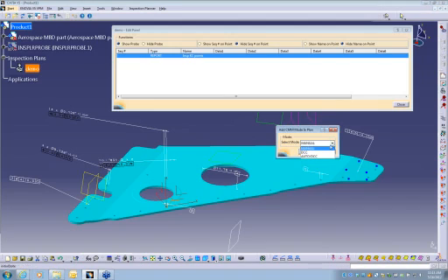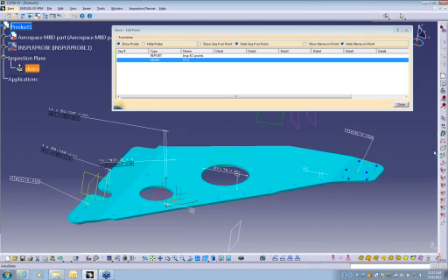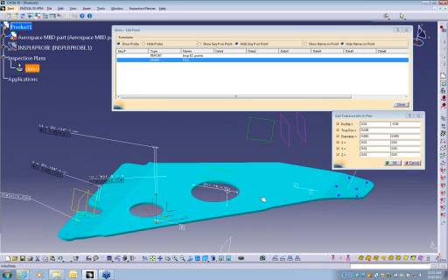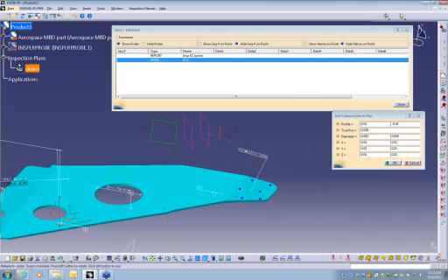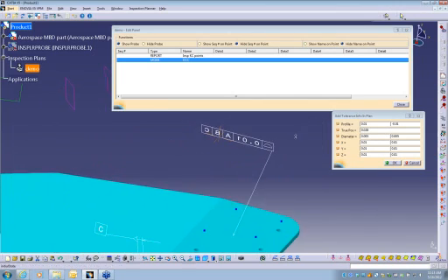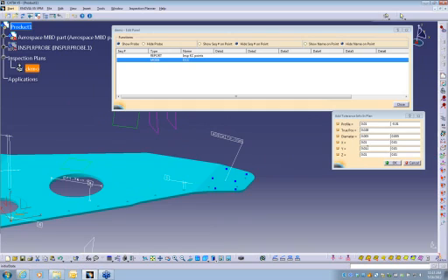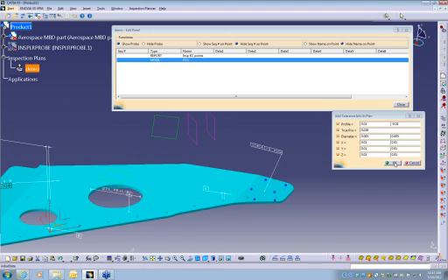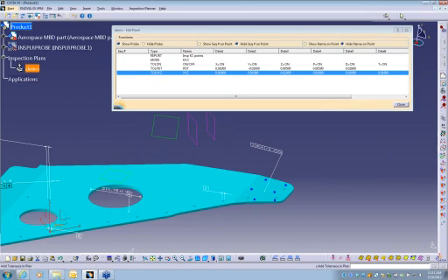We want to come in here. We want to put the machine in DCC mode. We can come in here and we're seeing the MBD tolerance right here. It's 10,000, so we can put the profile, so we can enter manual tolerances like this. We say OK, so we're creating the plan.